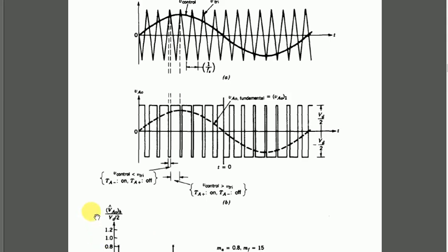Sorry, not the output frequency, the switching frequency. And then we have another signal which we termed the control signal. It can be a constant, as I mentioned, or it can be a time varying signal. Here it is a time varying sinusoidal signal because in this case we are assuming that we want the output to be sinusoidal. So we can see the relationship between those two here.